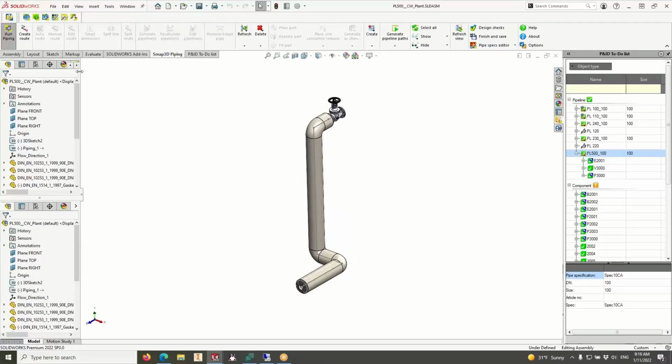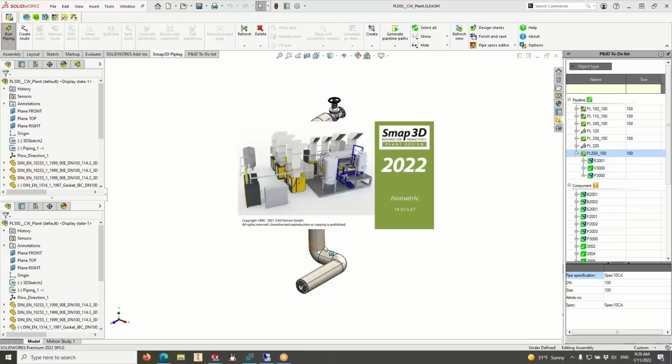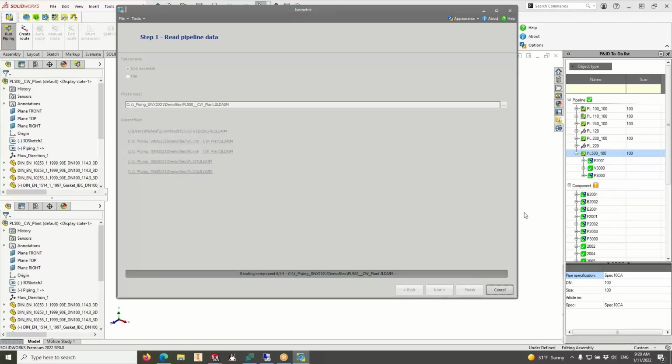You can go through and generate your drawings like you always would, or you can generate your isometric drawings. Now with the ISO, all we got to do is come in here and click two buttons, one to start ISO, one to hit finish, and it will go in and generate a single line isometric drawing here for you.